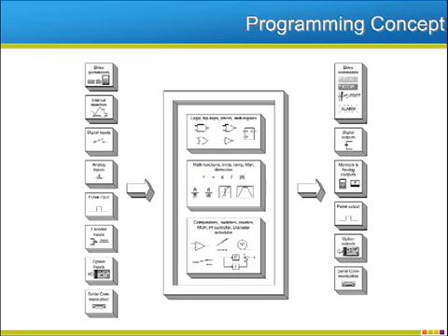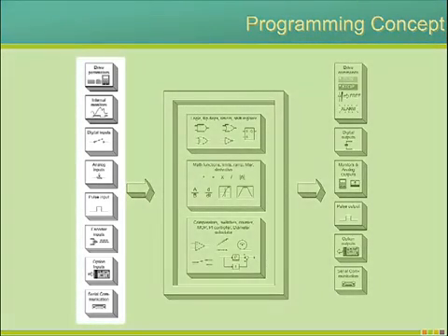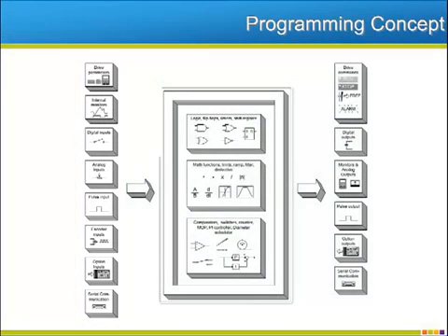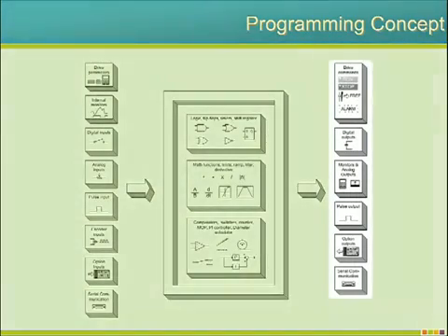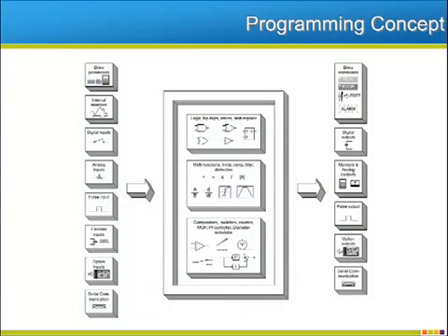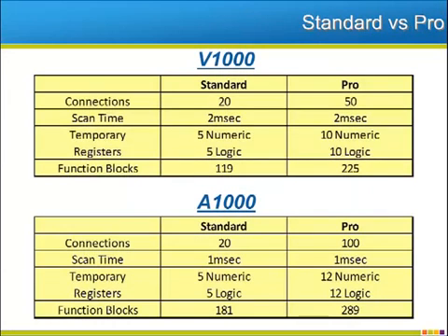The programming concept is simple. Start with an input, such as a drive parameter or a digital or analog input. Then modify it using an operator. Logic functions, mathematical functions, and limiting functions are some of the operation blocks available. Finally, send the result to an output. Among others, you can choose to close a digital output, send it to a Modbus register, or activate a custom alarm.